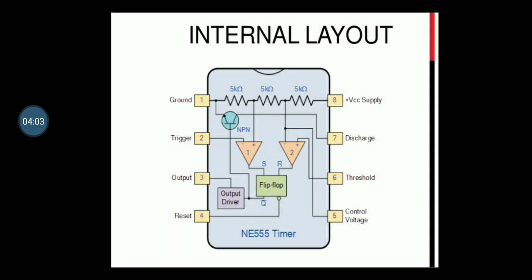It has 8 pins, starting from ground to plus VCC power supply: ground, trigger, output, reset, control voltage, threshold, discharge, and plus VCC power supply. First one, internal layout.